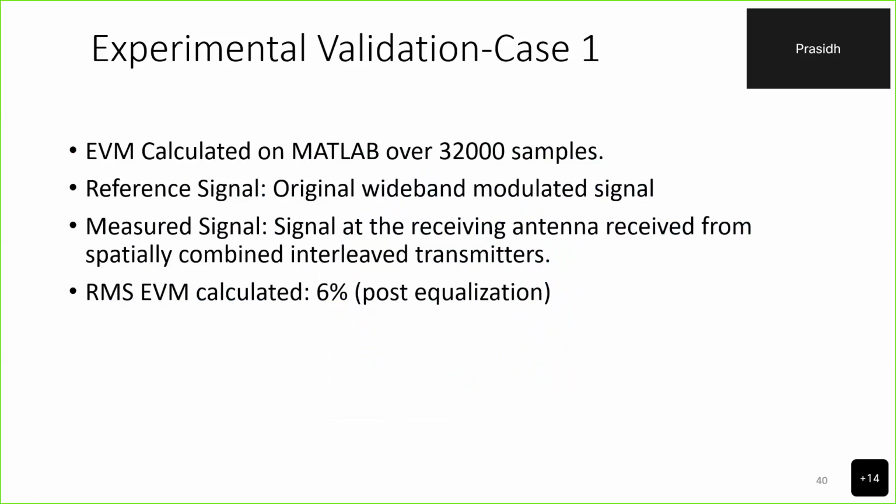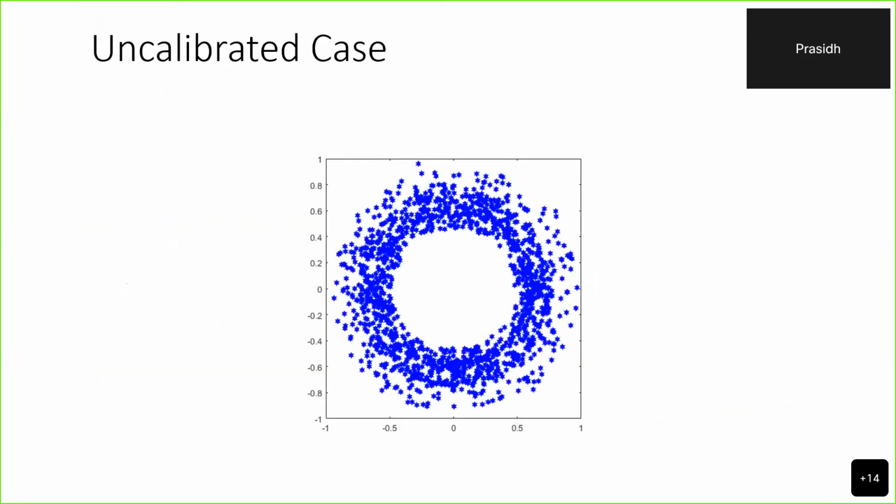Now, there is an interesting use case of this. Since I said that it's a single carrier modulation scheme, which is very sensitive to discontinuities in any part of the spectrum, if the beamforming is not done appropriately, or if one tries to capture a signal using an unintended receiver, then one is going to receive garbage. So it also has a potential to provide a degree of security in the physical layer.